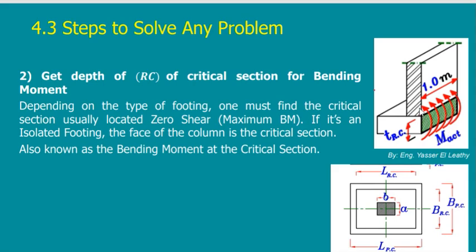If I take a section here and take off the part of the foundation from here, then the part I just took off exerts a moment in this direction. The part similar to this one in this direction wants to bend up. So how can I prevent it from bending up? By putting steel below to prevent the portion of the cantilever from going up after the column.